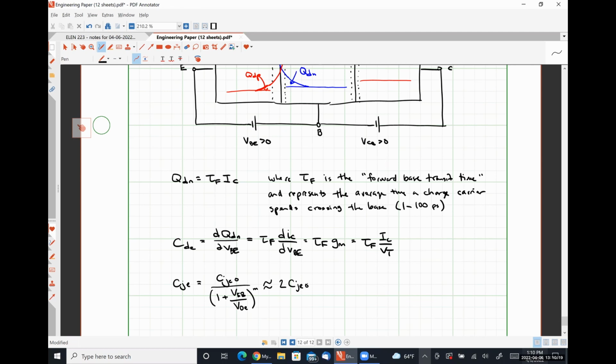So we're making this portion here take away from 1, making the overall junction capacitance larger. And for simplicity's sake, we're going to say that it's roughly this, because there comes a certain point where we can't make the width of the junction any smaller without messing things up. So we're going to assume we're operating at a point in forward bias where the depletion junction capacitance is roughly twice as large as it would be if we didn't have a bias voltage applied to it. Okay.